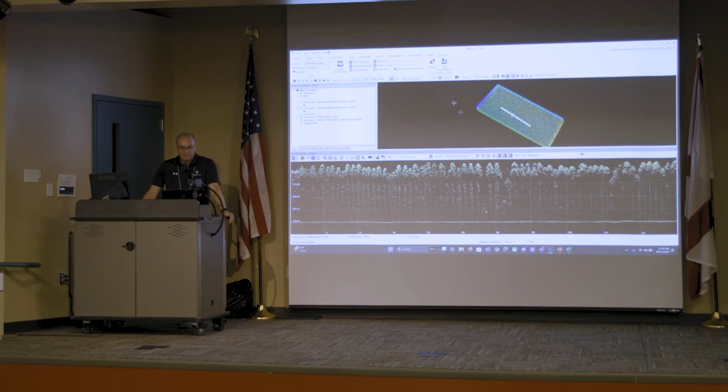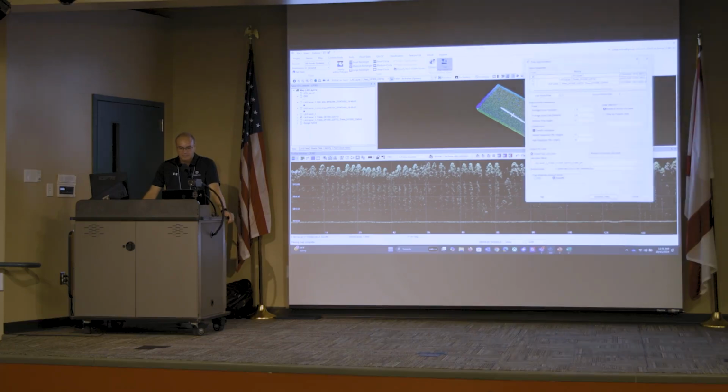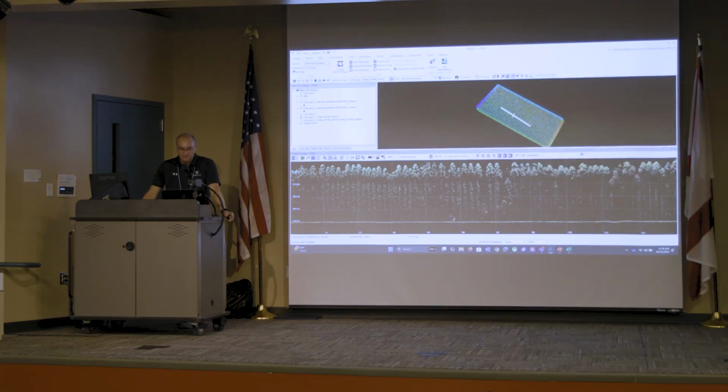So you basically use the information from here, and that's a good point to explain how the 32 channel works. The 32 channel helps us to get this kind of information, right? The base of the trees, you can visually see very well here in the profile window because of the 32 channels that we have on the 535. We don't have that on the 540, but on the 540 I have much more data because, as I said, it works with 500 kilohertz nadir to the ground, right?